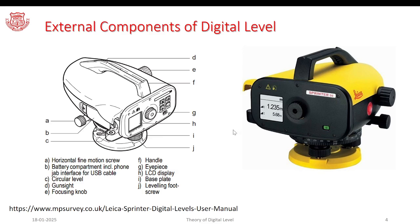Just recall the basic construction of the dumpy level, tilting level, auto set level, and the levels that you are used to. Essentially, it has a leveling head, a telescope, and a focusing mechanism through the eyepiece as well as the object glass, and a set of axes which bear the standard relationship. If that standard relationship is not observed during the temporary adjustment, we go for the permanent adjustment. This is partially valid for this equipment also. Here, the discussion could be extended, but I think it can be spared for a while.